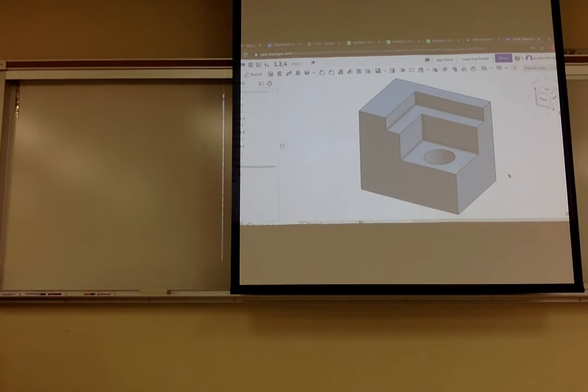Oh, the problem is you've already dimensioned, so it won't do what you want. So you highlight one at a time. Highlight actually this one, and then right-click. Show hidden lines. Now it works. It'll show you all the hidden lines. You want to see those. You should be able to. Yep, there you go. At the very top, show shading. Oh, it's blocking. It won't show the whole menu.